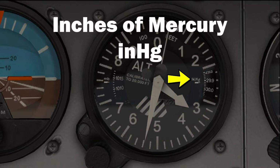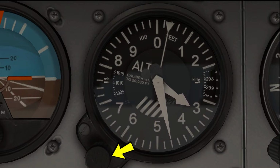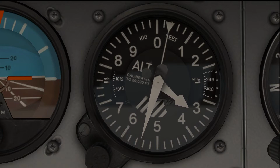In the US, it is measured in inches of mercury. On a clear day, it will be set to 29.92 inches of mercury. As the weather changes, air traffic control will announce a barometric pressure. You adjust your altimeter to match the number, and your altimeter will give you the correct altitude above mean sea level.